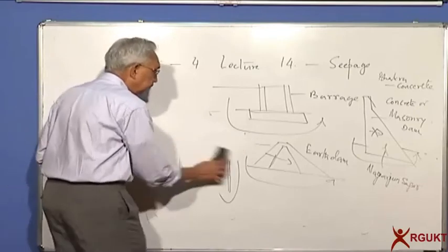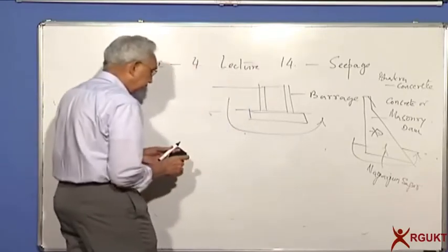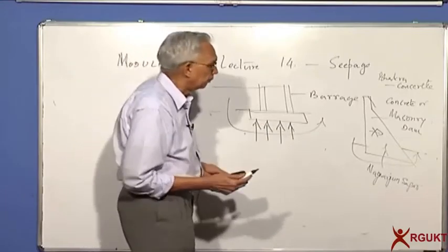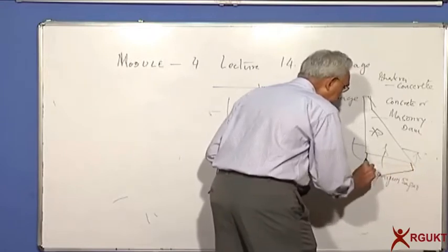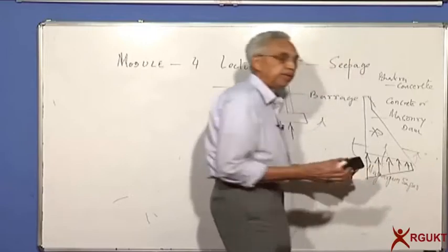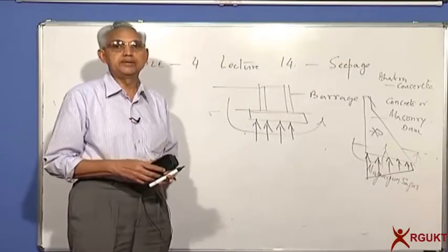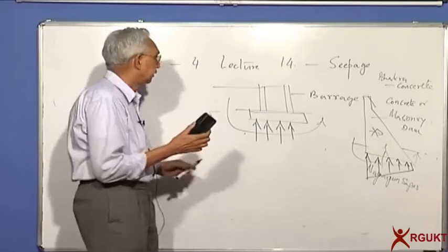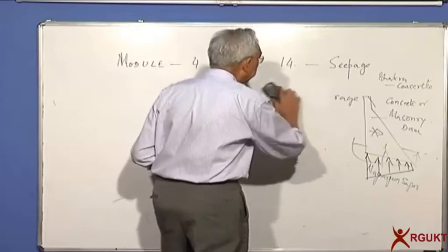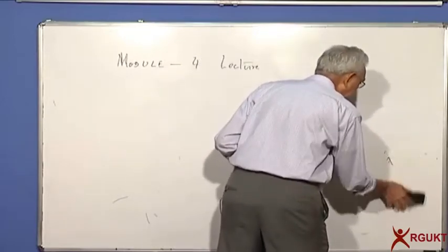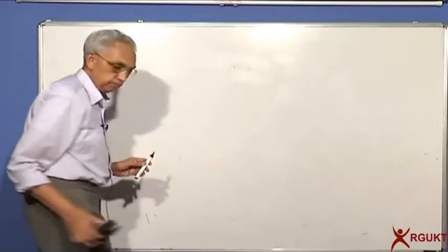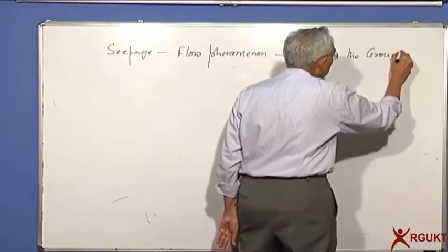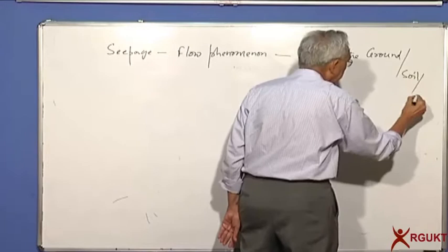For example, here on the barrage and the gravity dams, you will have what they call as uplift forces. The water pressure can lift the barrage if you don't design it properly. Similarly here, you will find that the uplift force can cause some damage to this gravity dam if you do not take that into account in the design. So all these are the parameters that we need to study so that you design a proper hydraulic structure resting on or inside the ground. So seepage is a phenomenon of flow through the soil. So let's look at the particular phenomena, and we are talking of through, of course by that I mean through either one soil or several soils.